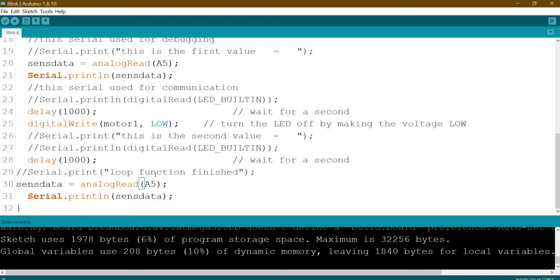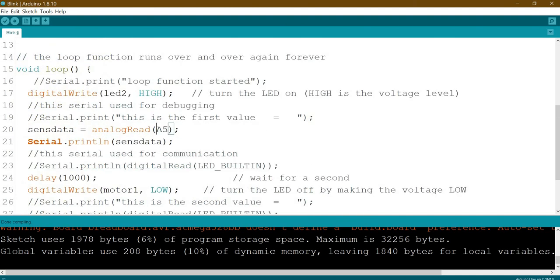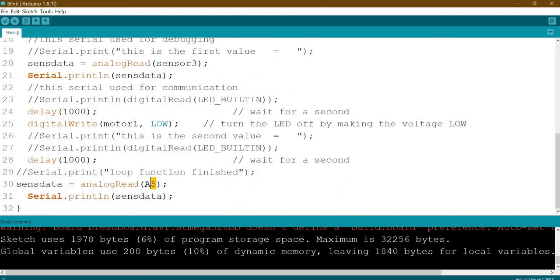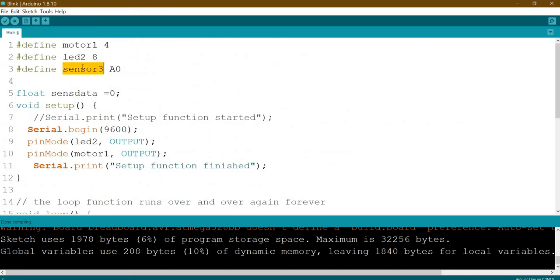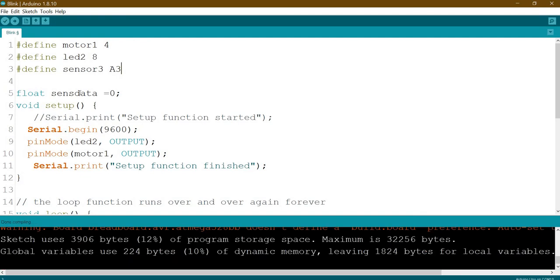And again, if you use different inputs and outputs multiple times, it's better to use text substitution. Then you can change it just once, and it will change in all the places you call it. So if I change sensor 3 after you've done your design and pre-design stage and they ask you to change this or add more sensors, or change this from analog to digital, then easy peasy, you can change from A0 to A3 and everyone will be happy, even your compiler, very fast.